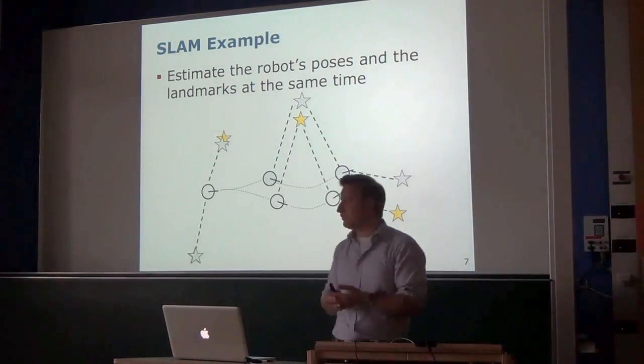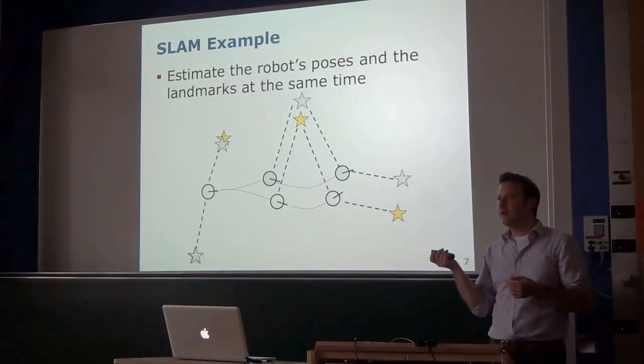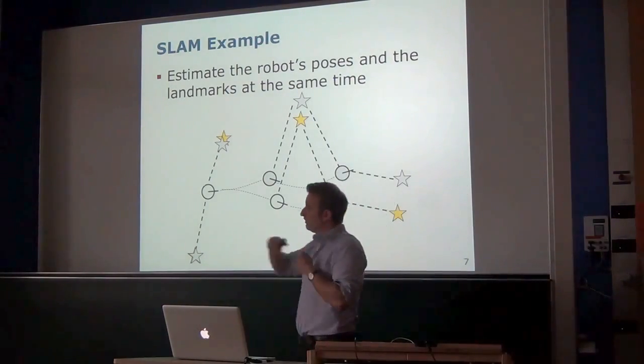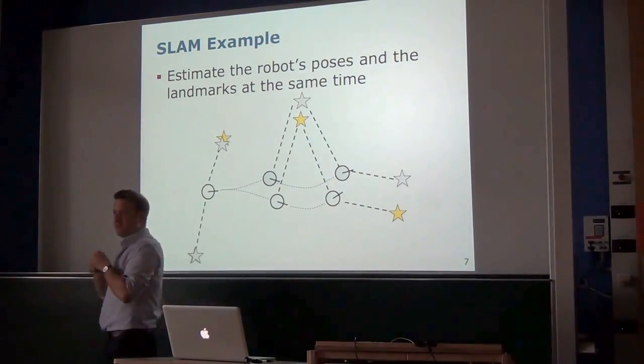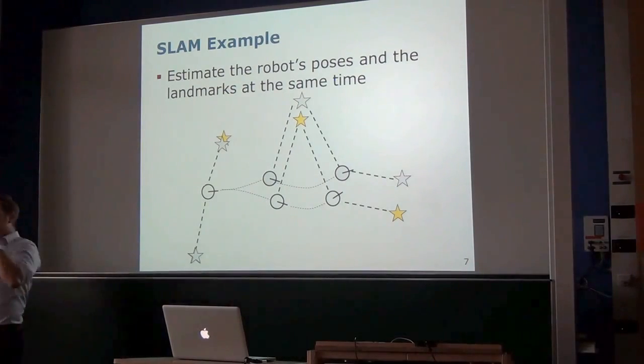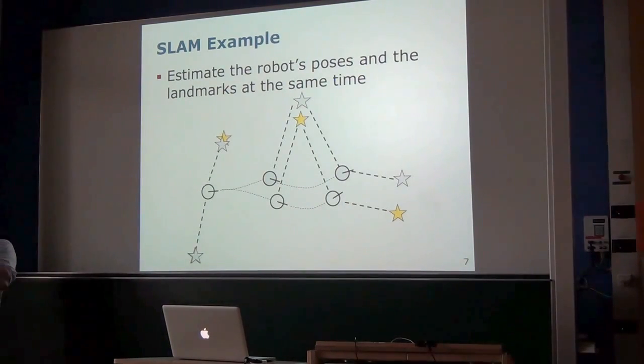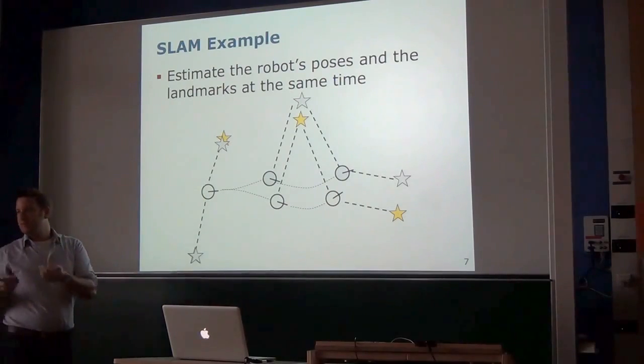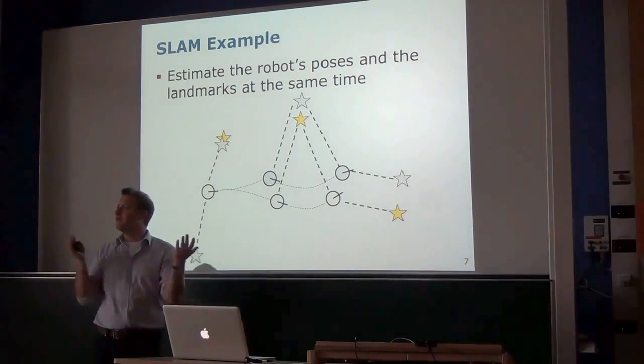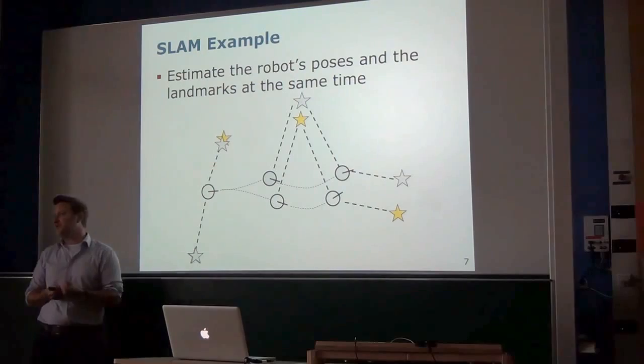Other sensors typically send out a light signal and measure the time until the beam of light or the laser beam hits an obstacle and is reflected. They just measure that time and can calculate the distance from that. But again, this is a measurement process, and the clock is not perfect, and you have errors in there. That's the reason why your observations are uncertain.